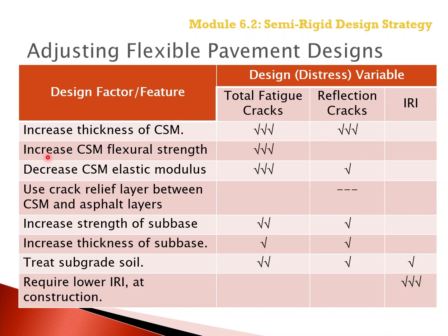If we increase the flexural strength of the chemically stabilized layer, we have a significant effect on the total fatigue cracking from the chemically stabilized layer, but individually there is no impact on the reflection cracking other than from the reflection of cracks from the chemically stabilized layer. So there is an effect, but it is related to the total amount of fatigue cracks, not specifically to reflection.